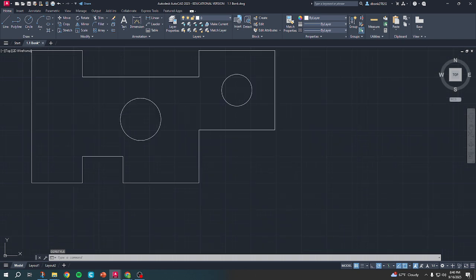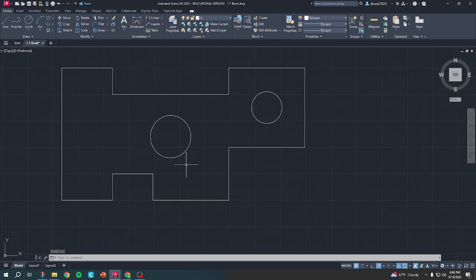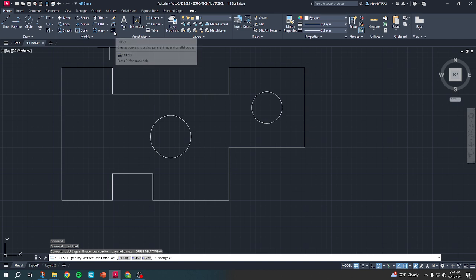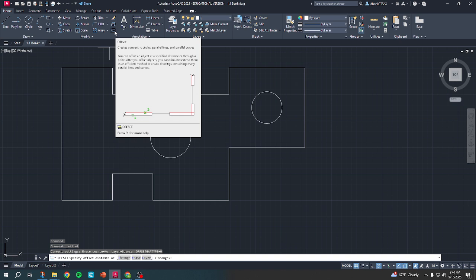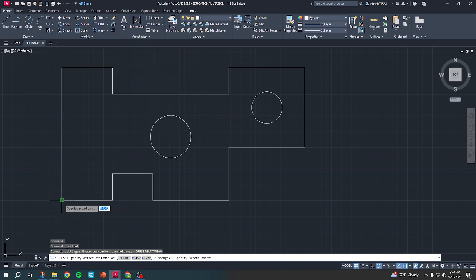So then step 2 is when you're dimensioning and you put a measurement on a line, it can go anywhere. So what you want to do is make a place marker for yourself. And the easiest way to generally do that is to learn how to use the offset tool. This right here, if you hover over it, it'll say offset. It takes a second to learn how to do this because it's a 3-click process. You've got to click on one end of something, another end of something, and then the object itself, and then it's going to allow you to push it in either direction.